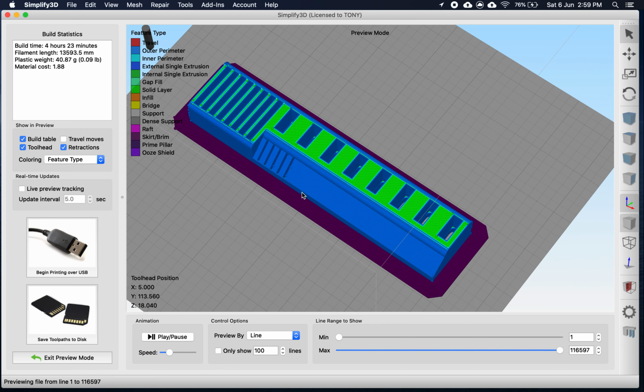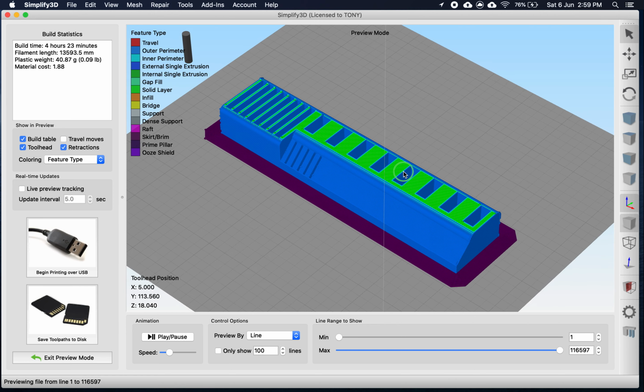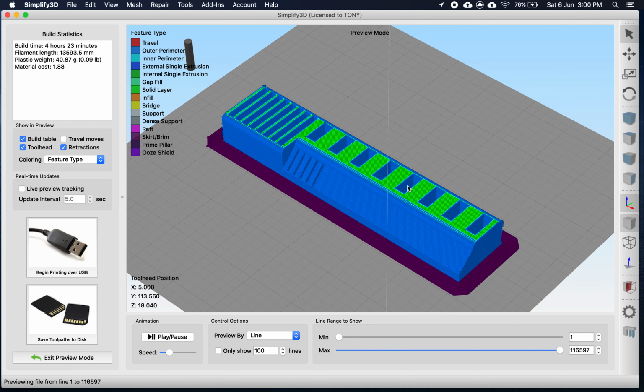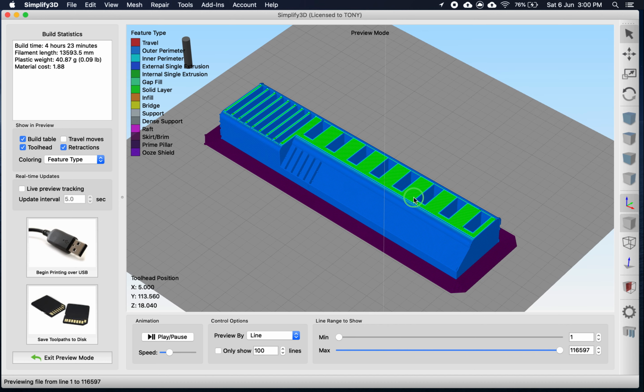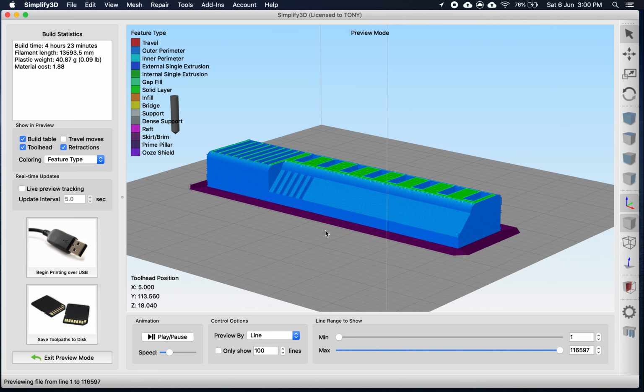For support, or for part design, I would recommend that you design with your printer in mind. Let's say the part you want to print, try to design it nicely for it to be printed out. Try to understand how the machine works. The machine will lay out nozzle and material layer by layer. So if your design has a lot of overhang without a nice base or something like that, then you will have problems building your part.